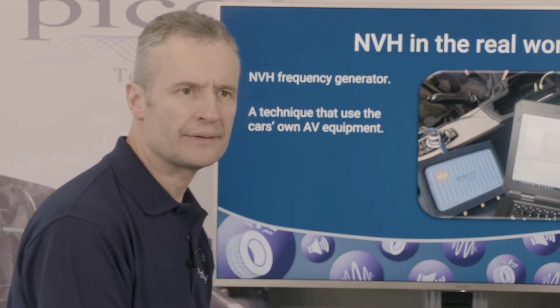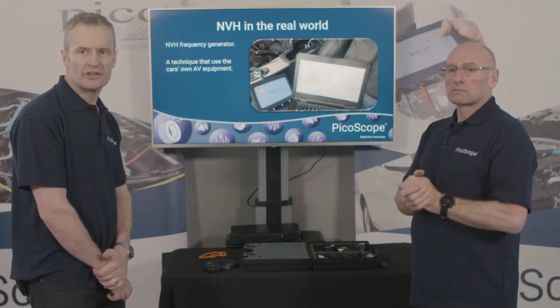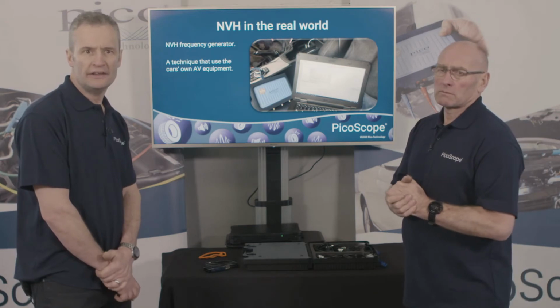With NVH, if you have a PicoScope connected, there's a feature within there called frequency generator, and we can use that to our advantage in a number of ways. One of the key options is to play any frequency from 0 to 20 kilohertz through the in-car entertainment system, aux socket or Bluetooth, depending on the style of system. The benefit is helping us find these elusive rattles, cabin rattles, trim rattles, creaks and squeaks.